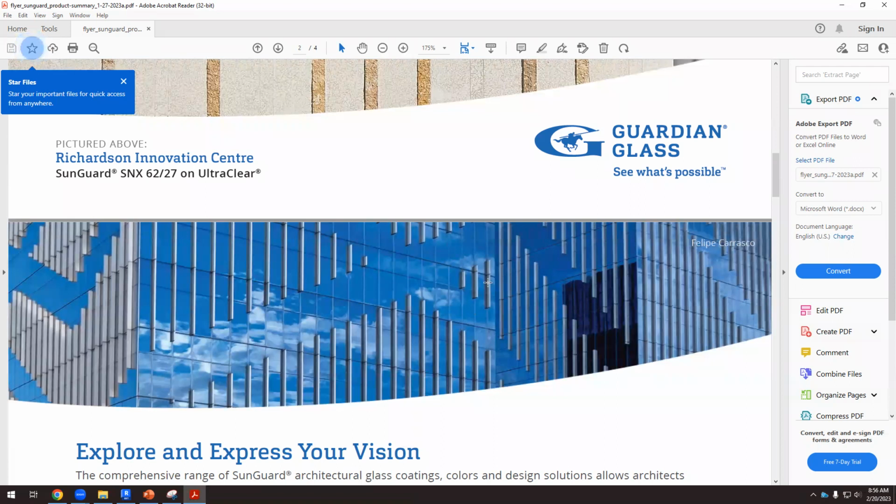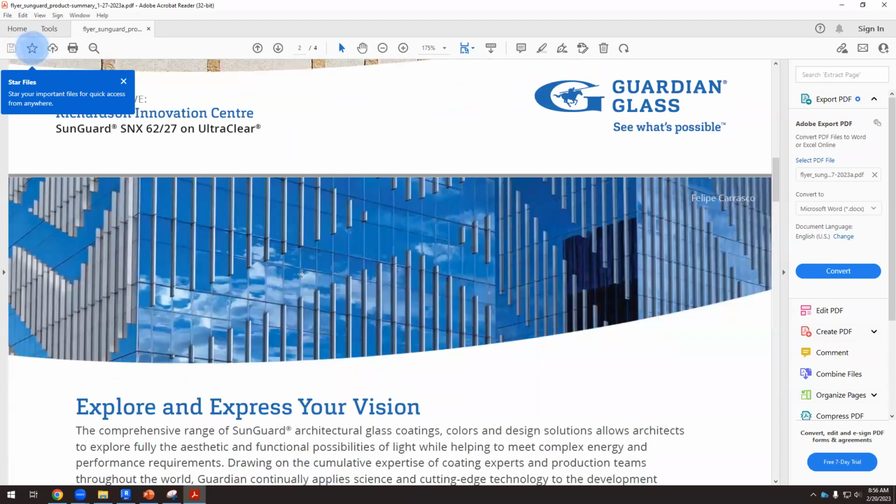Here, if you look at the south elevation, the curtain wall that we have, we have something like that, but they are horizontal. So that helps. In this case, I don't think it helps. But what we do see is that this glass is not transparent at all. It's like a mirror. So that means it has a very low solar heat gain coefficient, probably because the cooling loads were so huge. Then the first thing they did was to reduce the solar heat gain coefficient. So probably this is 0.2, something like that, because it's not transparent at all.